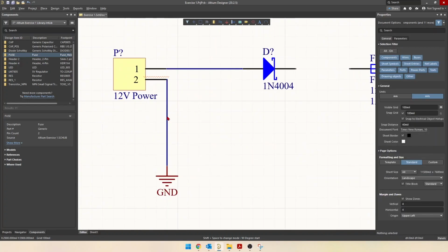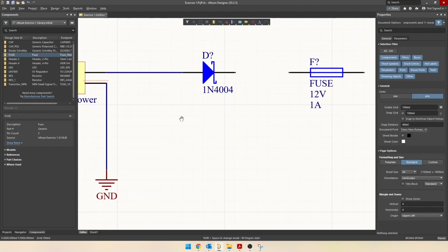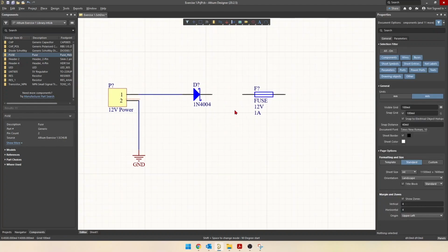Now to edit these wires, if you want to delete them, you can just click on it and it will bring up these little green boxes. Those are the points that it has snapped to, the snap points of pins and components. And you can click on that and move it about, drag things to rewire or change any mistakes you've made. Ignore that little squiggly line, we'll talk about that later. Again, click here to place a wire, right click to exit placement mode.